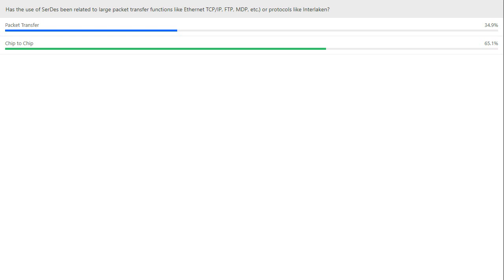Yeah, that actually surprises me. I was expecting it to be the opposite, and that's really great because there are different considerations associated with chip-to-chip versus packet. Packet transfers usually have to travel over backplanes, and they're long distance things. Chip-to-chip, we're literally talking on a PCB, point-to-point. And there are different considerations and concerns associated with that, one of them being the protocol itself that's used.